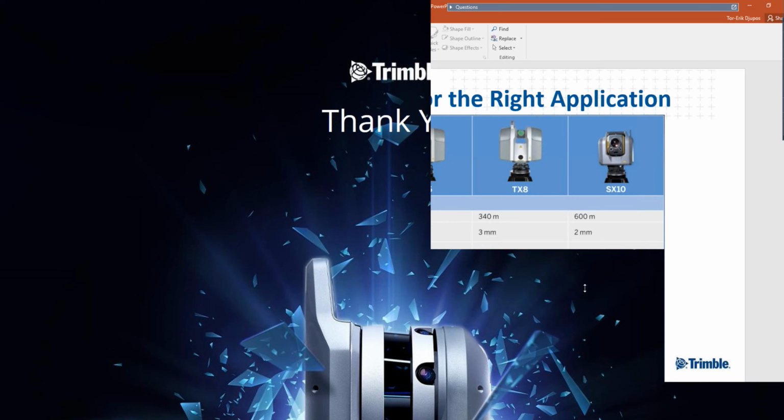Also, a question around the servicing, Ted. So, the statement is, it never needs servicing. Well, a service and calibration are two different things. A service can be the mechanical side of things. Calibration is the process which normally you have to send it back to a factory for, because of the tools needed to run it through that, to take the measurements and apply these deviation reports and all that kind of stuff into the laser scanners. That's the calibration process.